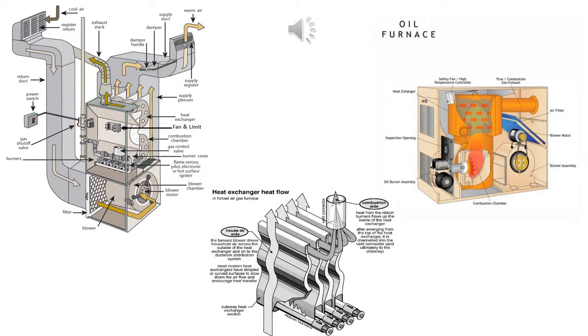The flame sensor is a safety switch. It is a device that tells the furnace if a flame is present. If the sensor does not sense a flame within a set time, it will stop the ignition and delivery of fuel to the appliance. It also will not allow the appliance to start the ignition sequence if it senses a flame when there is not supposed to be a flame.